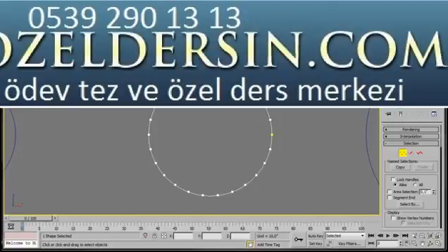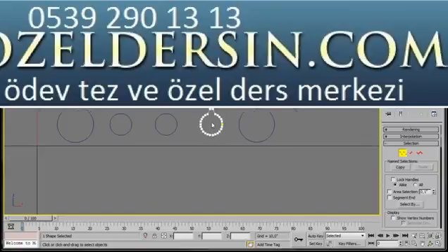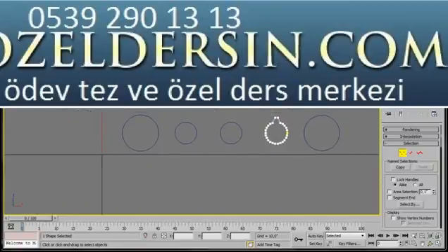Right-click, and now from the Flyout menu, click on Corner. Now we need to select the 2 center vertices, and we're going to drag them up. Look down in the Transform dialog and bring the Y-axis up to 0.59 or 0.6, something like that. Right-click, and we're going to convert these 2 vertices to smooth. Here we are, now we have a lovely shape for our spout. Okay, let's go over and turn off our editable spline.